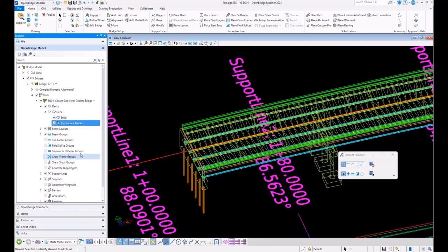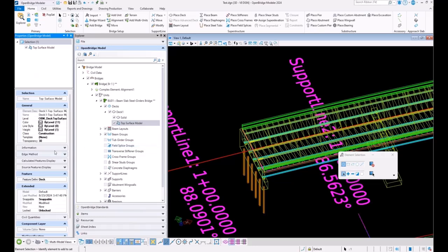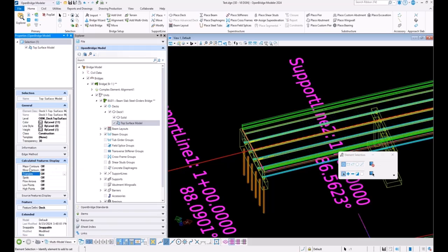Now, to control the generation of the terrain, the contour spacing that you want is through an element template that is being used to do this calculated feature. Again, it's treated like any other terrain, as you used to do in OpenRoads, for example, when you create one. So all of that is created automatically. And as I said, this is done through an element template, all the configuration of contour spacing, contour symbology, and the generation itself, what elements are displayed right as you create them.